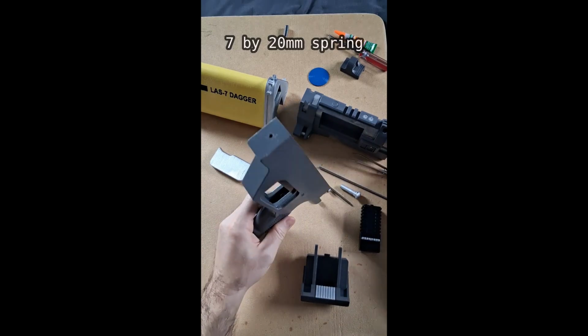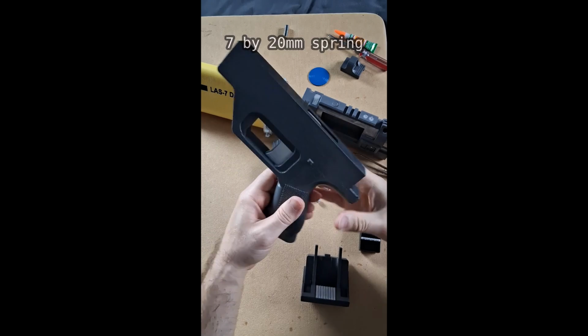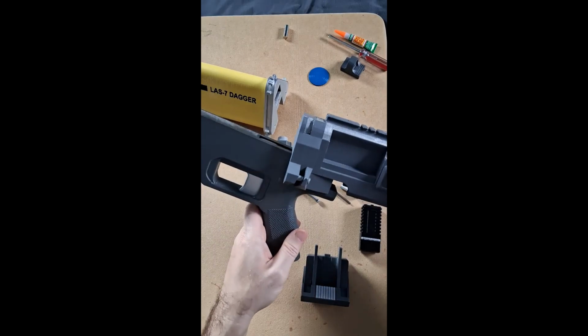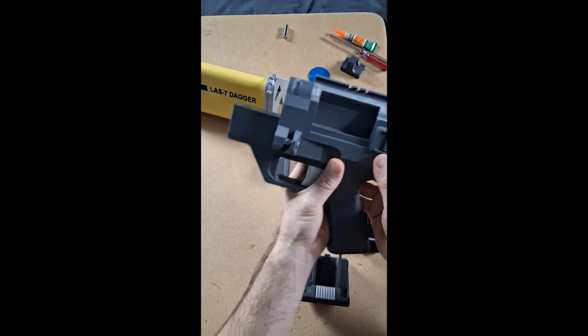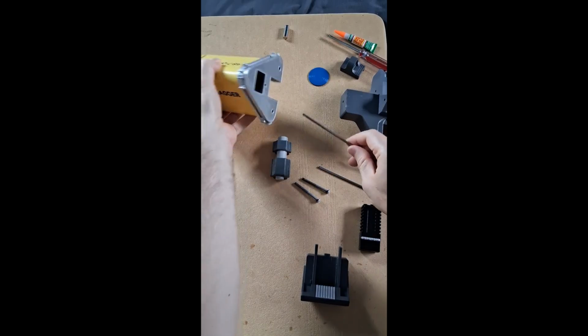First thing is setting the trigger spring, which is a simple compression spring 7 mm wide and about 20 long. This is set into a recess in the handle. Then you can slot in the trigger, leaning it forward as you place it so it doesn't dislodge the spring. Next, you can slide on the rear portion. You'll want to be gluing this as you go. I'm not gluing things together just yet.